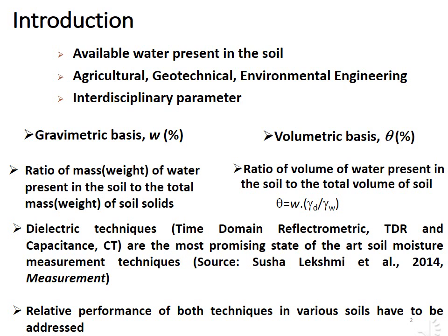I had carried out an exhaustive and comprehensive critical literature survey on the state-of-the-art technologies for measuring the soil moisture content, and the review was published in the International Journal Measurement in 2014. From the study, I could synthesize that dielectric techniques such as time domain reflectometry (TDR) and capacitance techniques (CT) have gained much more popularity mainly due to the dependence of the dielectric constant or apparent permittivity on the soil moisture content. For dry soils, dielectric constant varies between 2 to 8 and for water it would be 81.